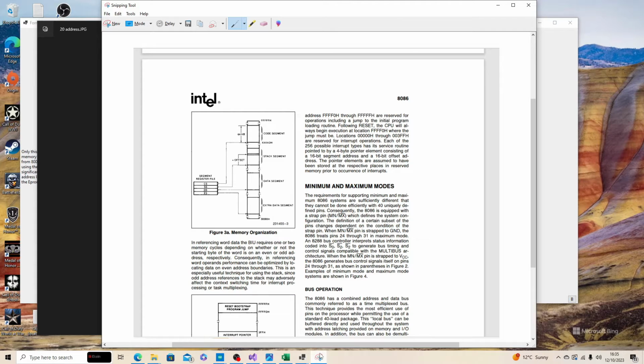Here on the same page, the datasheet mentions that on reset, the 8086 starts at address FFFF0, so 5 bytes. I'm only using 64K, so I'm effectively ignoring that first digit. I'm only interested in the last 4, which make up the 16 bits. I have no choice but to accept the FFFF0 location, as that's where the 8086 starts.